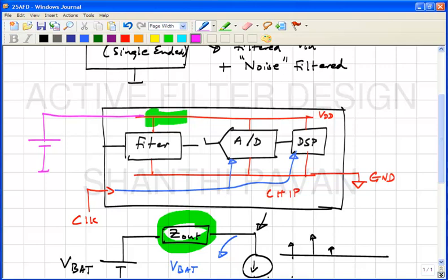Pardon? So, if the inside wire is dominating, then this will help. However, do you think the inside stuff will dominate or the outside stuff will dominate? The stuff outside will dominate. Though I draw it like this, in reality, the internals of the chip will be very small and the external of the chip, this part, is going to be very, very large, right? So, if this inductance dominates, which is what will happen in practice, whether you route the supply there first or here first makes very little difference. In practice, going forward, one could say it doesn't make sense to route supply like this.